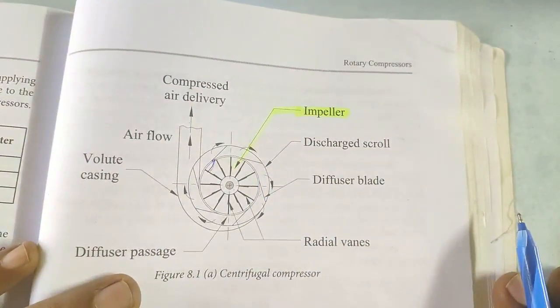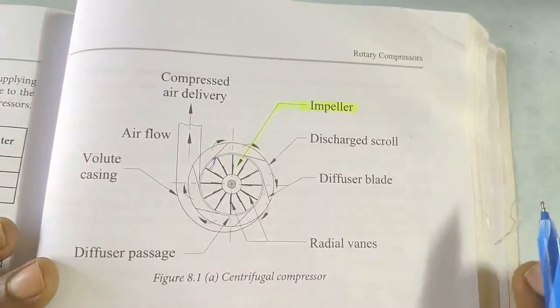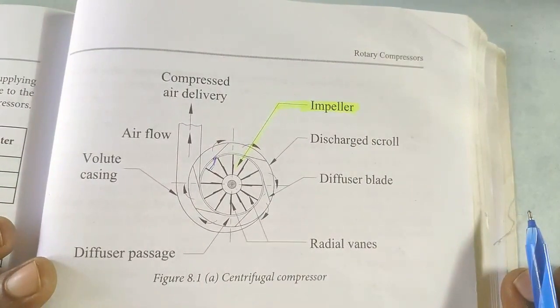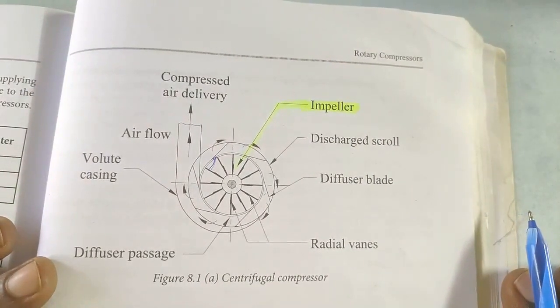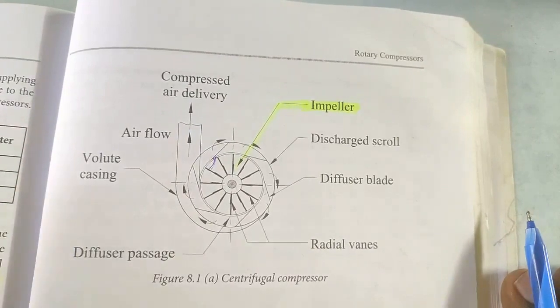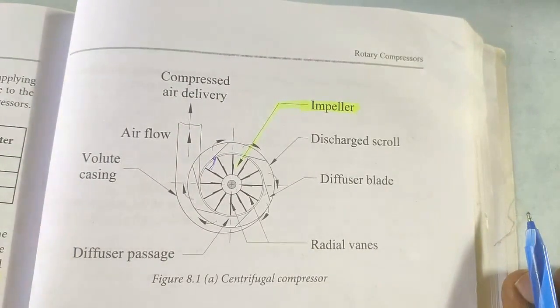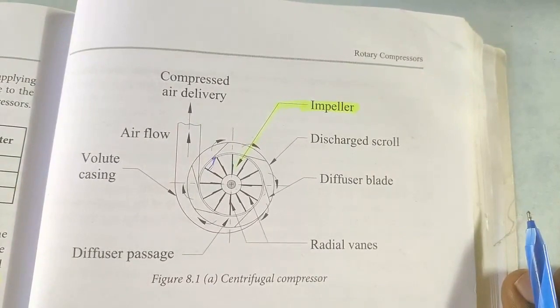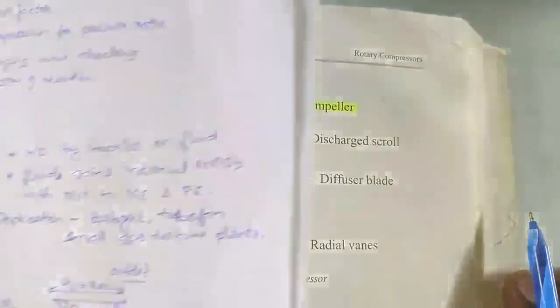The function of the centrifugal compressor is to provide air with a higher pressure ratio. Work is done by the impeller on the air, by which the air gains energy, manifested as a rise in kinetic energy and pressure energy. The applications of this centrifugal compressor are in turbojets, turbofans, small gas turbines, etc.